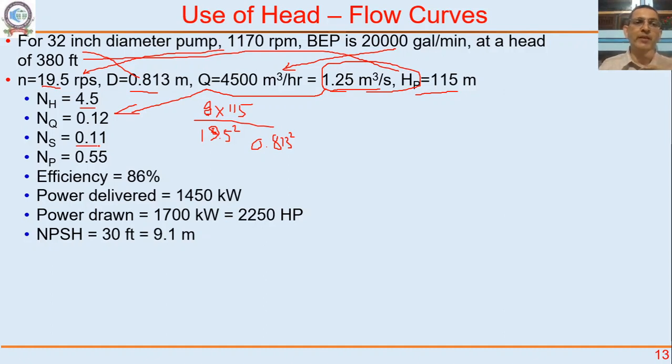That will tell you type of impeller. Depending on the impeller type, specific speed will change. So alternatively, if I know the specific speed, what specific speed I want, depending on how much flow and head I want, I can say, I will choose this type of impeller. Right now, let's not worry about that just now. Power number NH multiplied by NQ, 0.55.